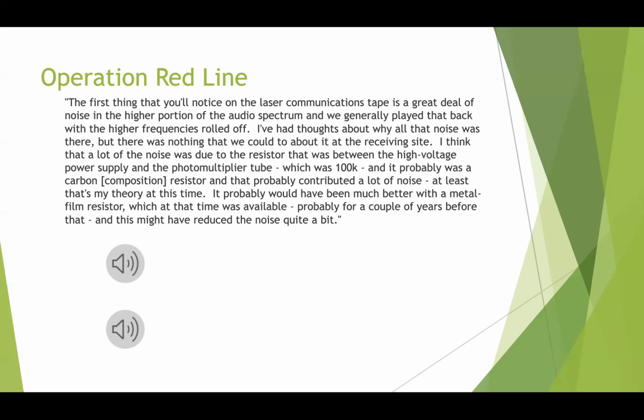Keep in mind, this is 50 years after the event that he's recounting this. It probably would have been much better with a metal film resistor, which at that time was available, probably for a couple years before that, and this might have reduced the noise quite a bit.